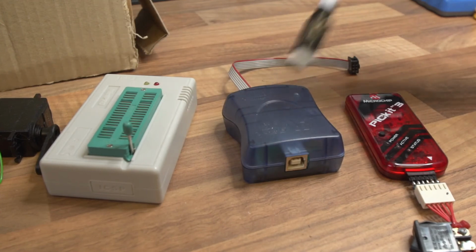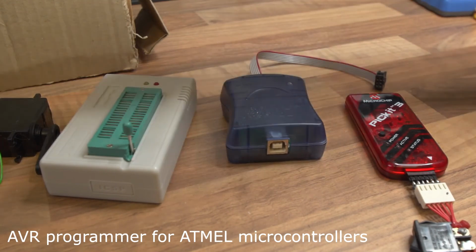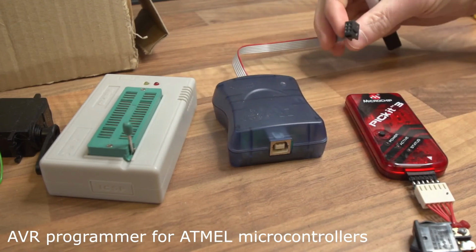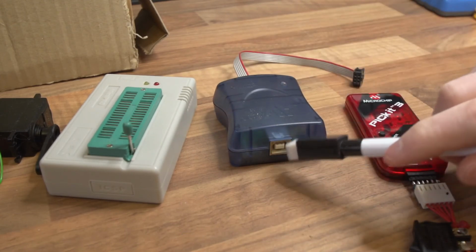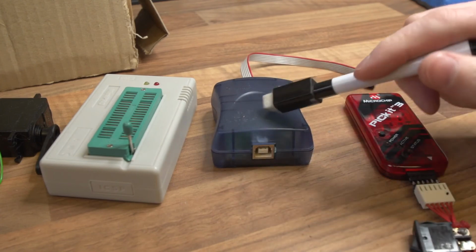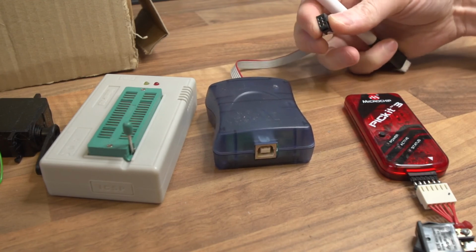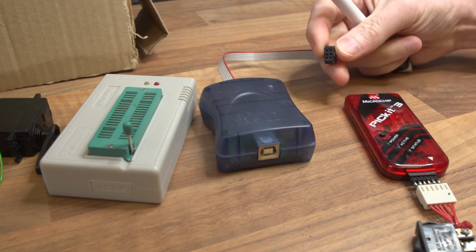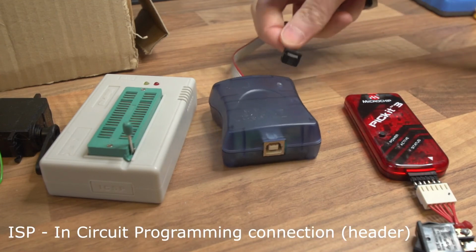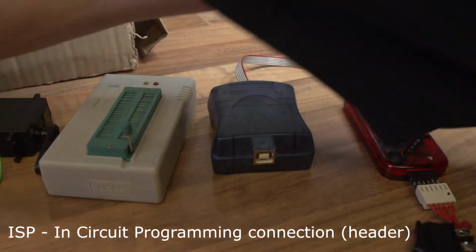This one is an AVR programmer. This is designed for programming ATMEL devices like the Arduino that I showed you earlier. And this has got a little header on it. Again, it's USB in from the computer. It comes with some software for your PC through the USB connection, and a little ribbon cable with a little connector on the end, and that can go to what they call an ISP, which is an in-circuit programmer DIL header. You can put that onto your board and you can program the chip while it's actually in the board. In fact, I've got one over here.